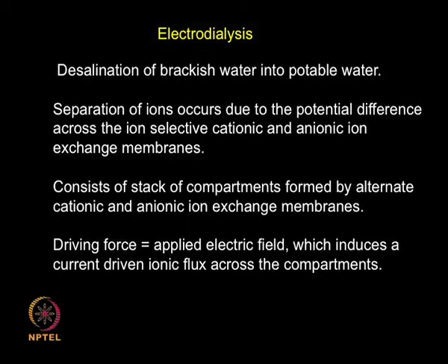Separation of ions occurs due to the potential difference across the selective cationic and anionic ion exchange membranes, as I mentioned actually. So it will have a stack of compartments, sometimes you will have 20-30 stacks actually, and each stack will have alternating membranes like cationic, anionic and so on actually.